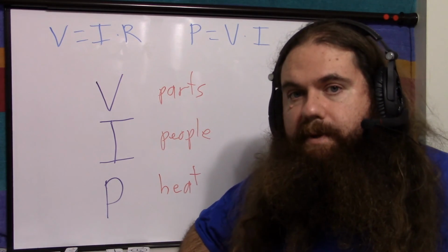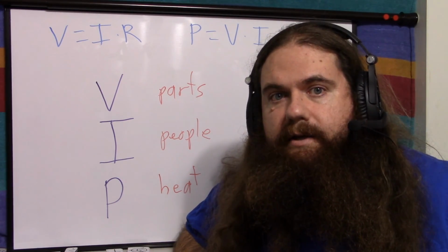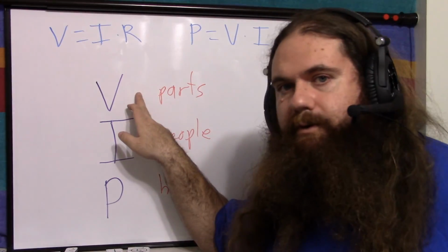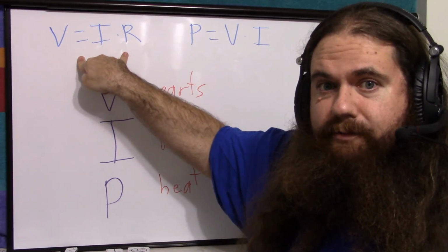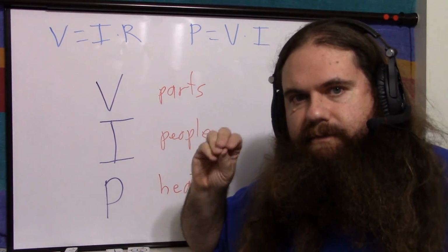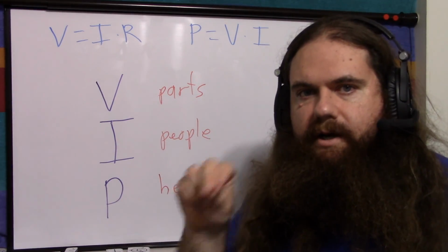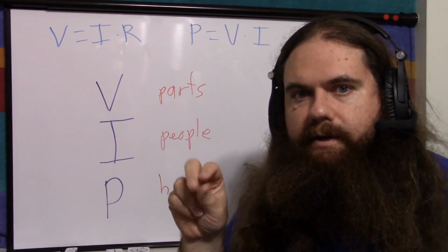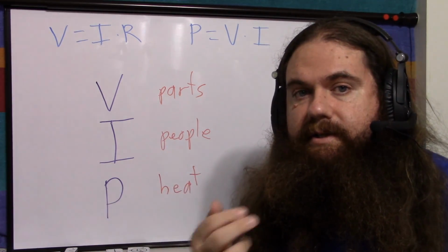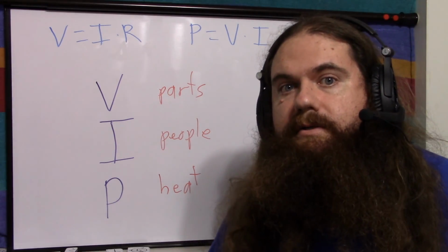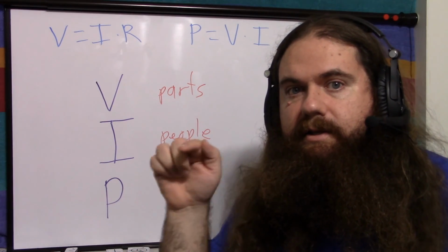Now, of course, this leads people to say things like, it's not the volts that kill you, it's the amps. If you say that, you're an idiot. Don't say that. Voltage with resistance causes current. It's right there! The human body has very high resistance, which is why I can just touch a battery, or just touch the ends of my bench power supply if it's on a low voltage. But if my hands are wet, it conducts better, less resistance. People put batteries on their tongues to get a little tingle because it conducts better. There's all kinds of electrolytes in there that love to conduct.